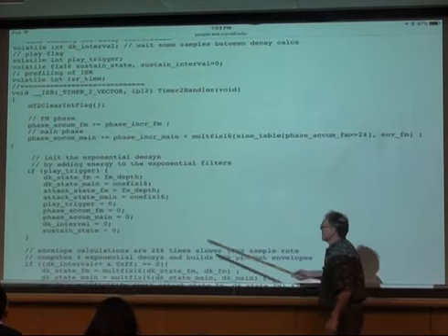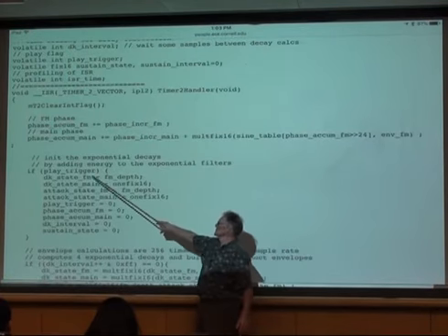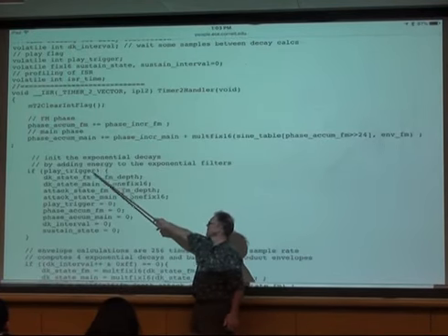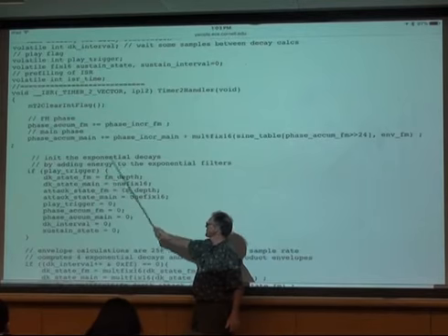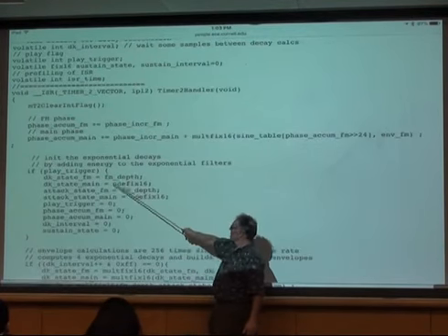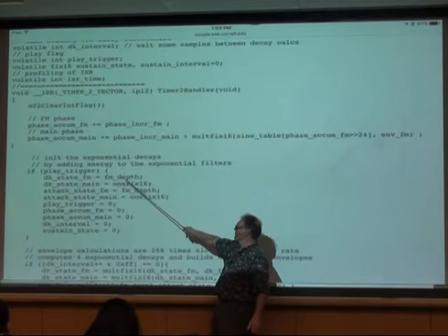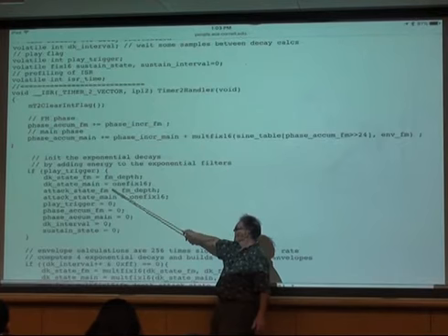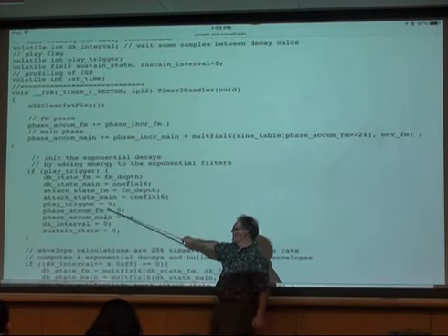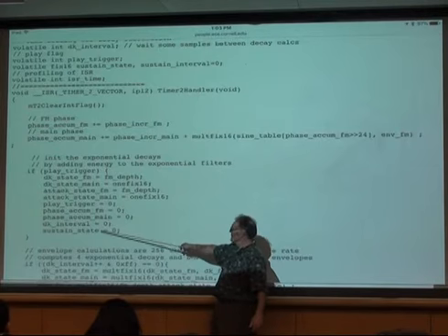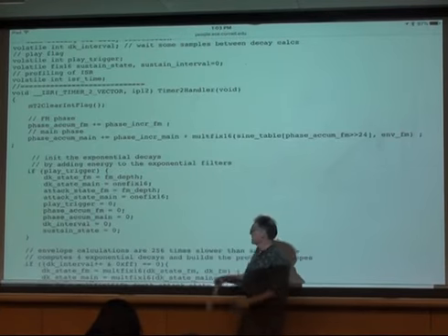And to play the thing, there's some input to this, which is a play trigger, say a push button that a human would push. You increment the decay and the main for the FM and the main to their appropriate values. You initialize the attack. You set the play trigger back to 0. You zero the phase accumulator so it's phase locked. And then there's a couple other counters.